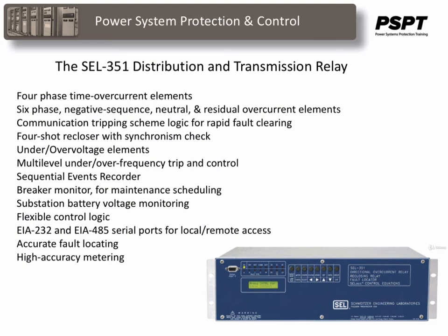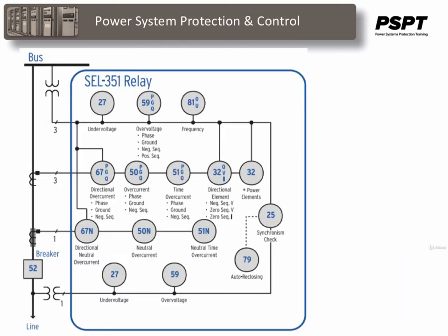So these relays are extremely flexible, primarily because they're like a small computer, but they do still look after the old logic of directional overcurrent type relays. And having said all of that, this essentially is what the relay looks like in its logic circuit and one-line diagram when it's plugged into the system. You can see that it does a whole lot more than just overcurrent protection.